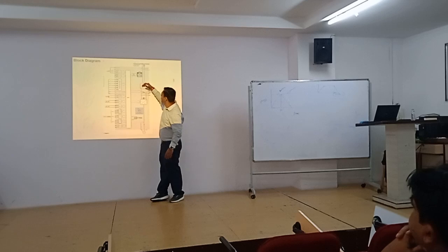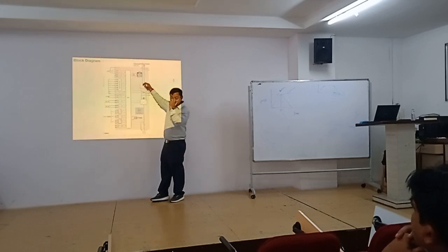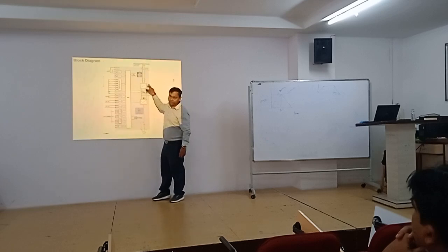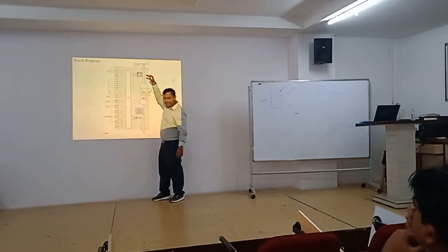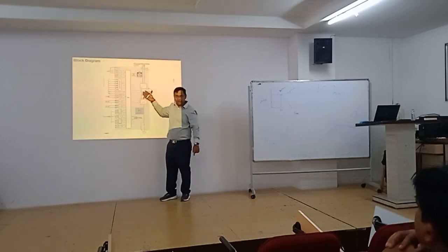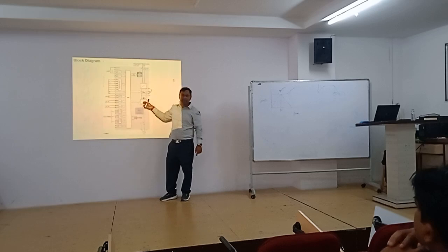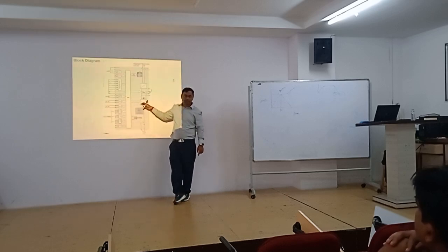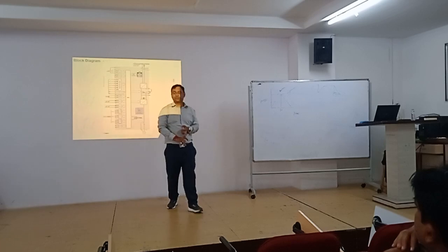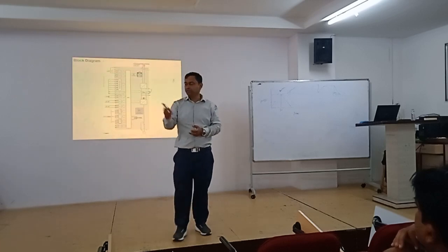So the very first thing that you do is make AC to DC. If it is three phase supply, then we will go for a three phase converter, which converts AC to DC. So you have the DC link voltage, you know. Again, from the DC we will make our AC by using an inverter. Inverter is one of the components in the drive. The inverter only will change the frequency and will also change the voltage.